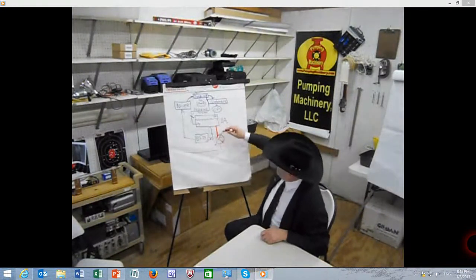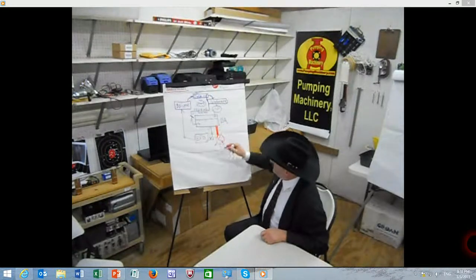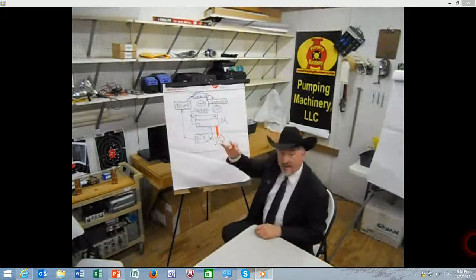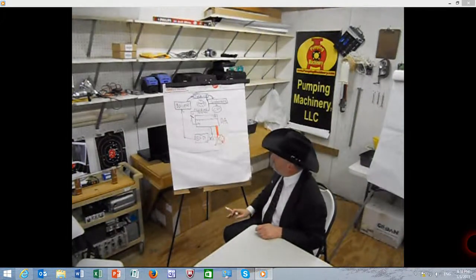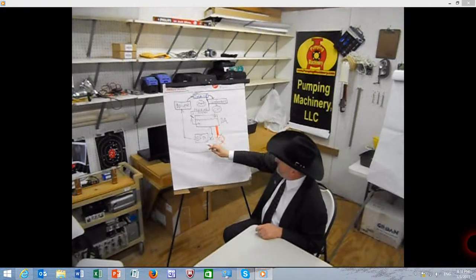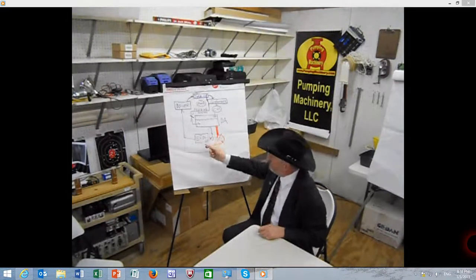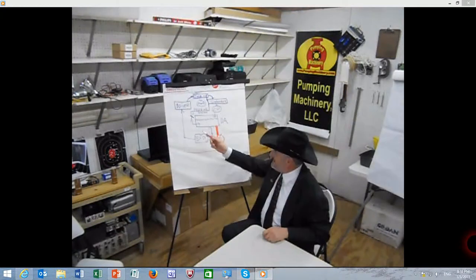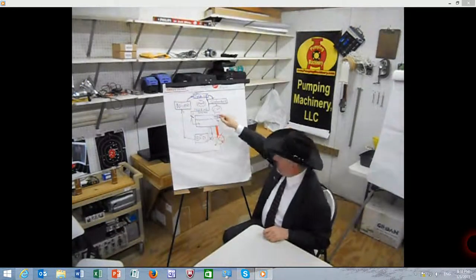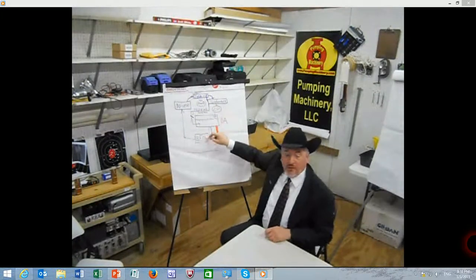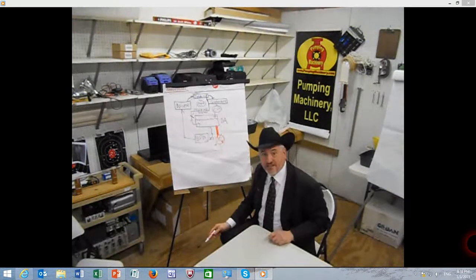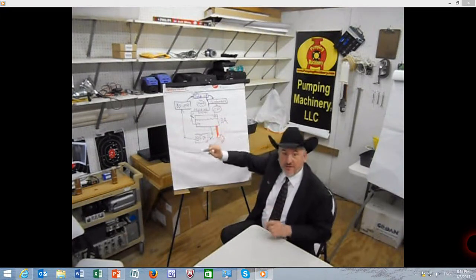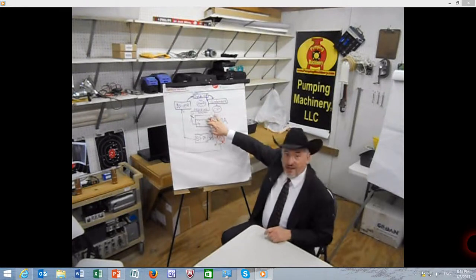And this pump shuts off. So the fluid collected in the suction header, which could be 100 feet in length, or the height to the DA, that fluid is hot. The fluid in the suction header leading to pump number 2, which is still operational at this moment, keeps getting cooler as the DA receives colder water. That colder water keeps on pumping to the boiler through pump number 2. That pump runs just fine because saturation is at a lower pressure and temperature, but still in saturation condition, remains at the DA.